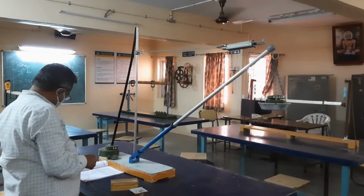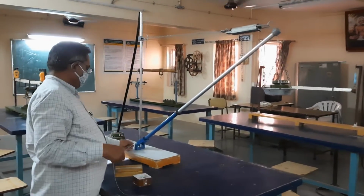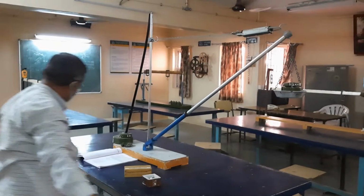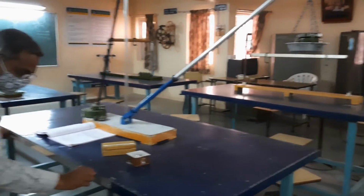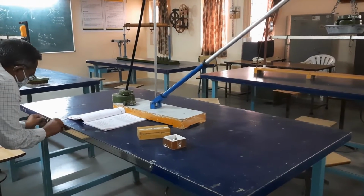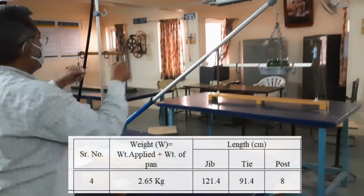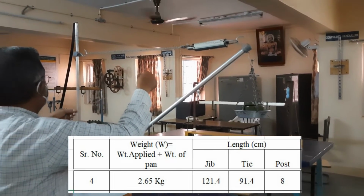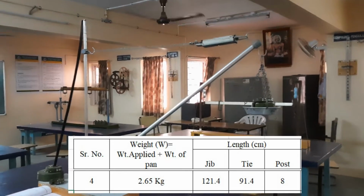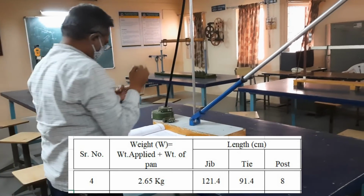Then for the next reading, the load is 2500 gram and the weight of the pan is 150 gram. Now we measure the length of the jib. The length of the jib is 123.4 centimeter and the length of the tie is 91.4 centimeter.